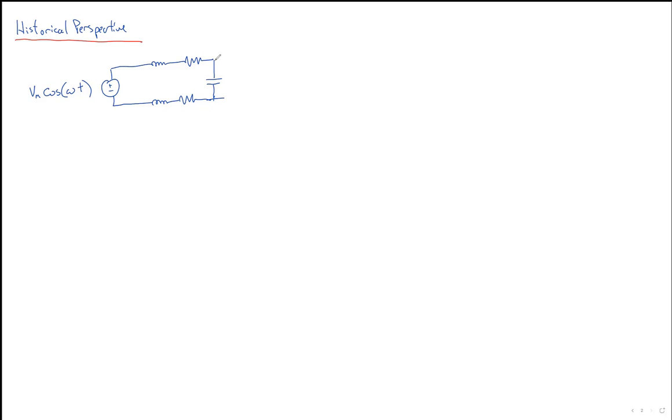And that might be a good representation of a mile of parallel lines. So the next mile might look like another set of resistors, inductors with a coupled capacitor. And now you've got a model of, say, 2 miles of power lines, and you're already up to a 1, 2, 3, 4, 5, 6th order circuit. So you can see the problem.